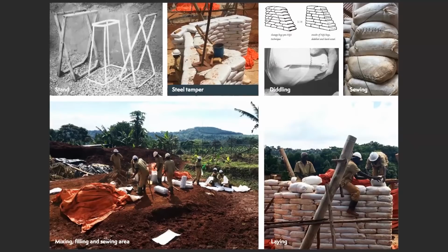It's also very important as you build with earth that you maintain the height of these fields and the compaction so that you can achieve continuous layers. I can't say that we have done it so well, but we have managed to at least layer these bags in a way that is very consistent. Of course, if you fill too much or too little and you lay these things down and compact, you might end up with either a wider wall or a thicker bag, so you lose the layering in that way.